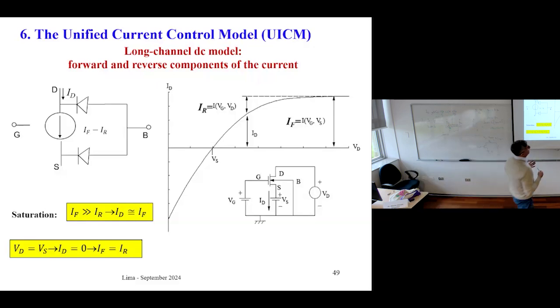But you should keep in mind that the determination of the forward current is here at some saturation of the characteristics. But in the real case, you don't have this real saturation. You have something similar to saturation. But assume that this curve varies, say, not more than 5–6%. Then you can assume without much error that I can take some value here and say that this is IF. But what about IR? I cannot conclude. It's a very small value, but how much? It's difficult to say how much.